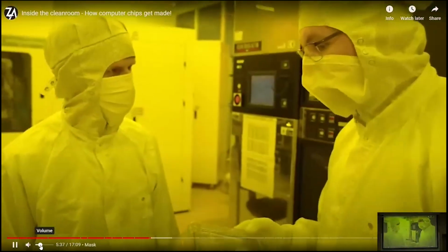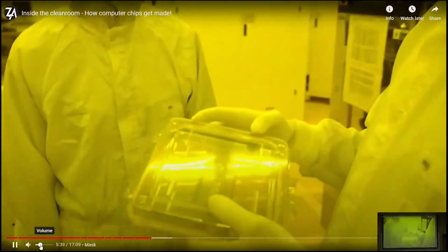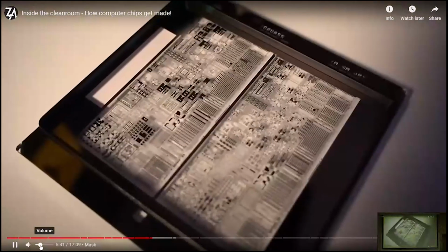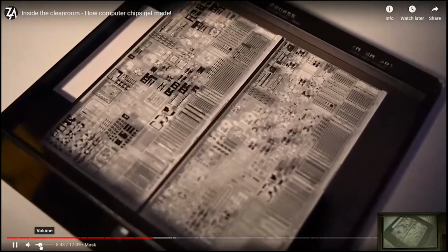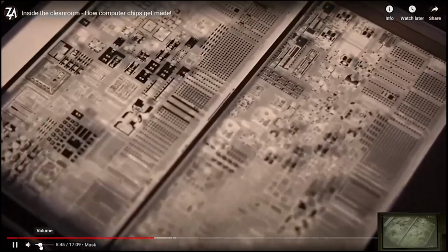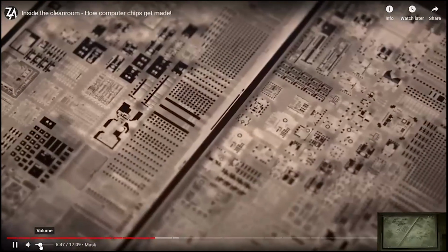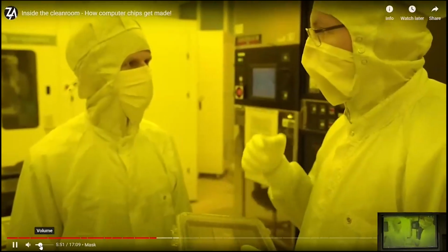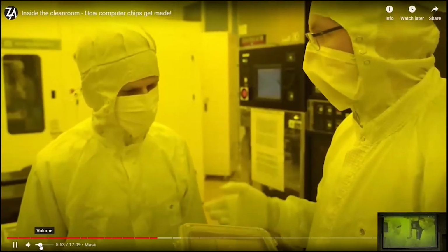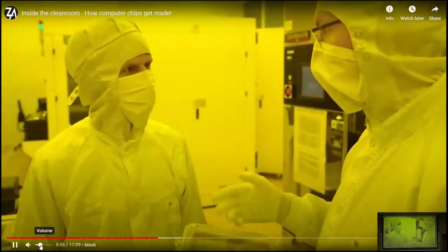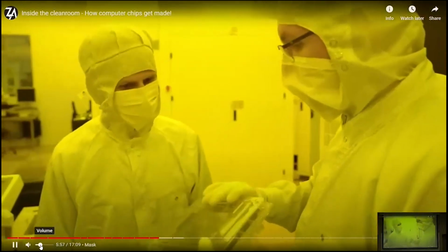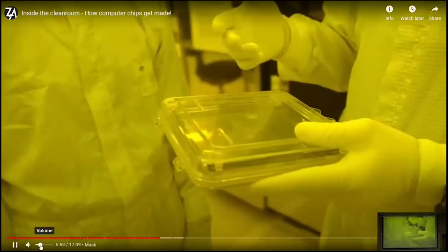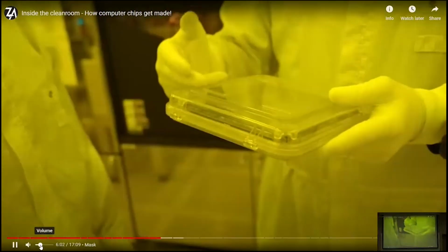This is a photolithography mask. This is a quartz glass substrate with a thin layer of chrome on the backside, and we also see here a frame with a very thin foil to avoid particles being placed on the chrome, which we would see when exposing, which would lead to imperfections like short circuits or interrupted metal layers. And on this reticle we have 3 different masks we can use for exposure for 3 different layers.